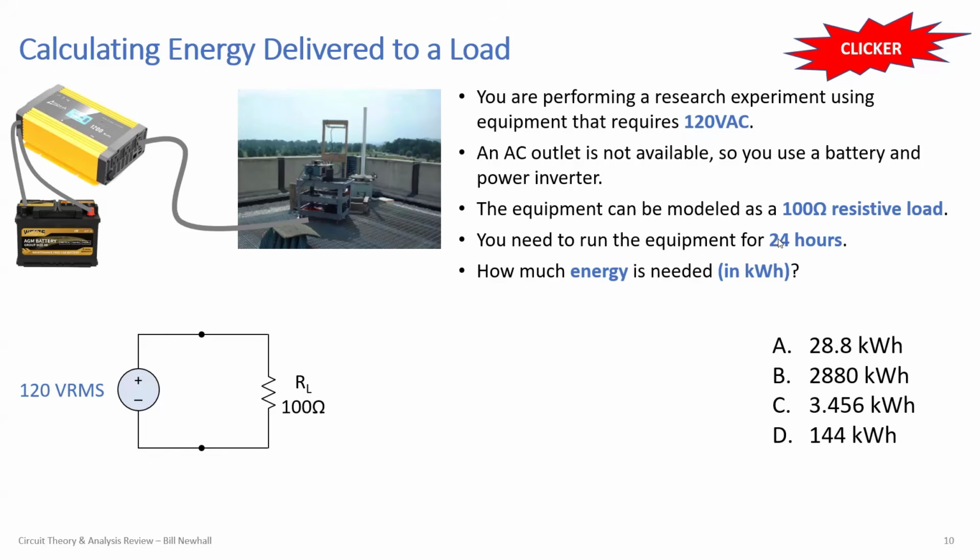All right, take another minute. And so a lot of these calculations can be dissected by the units. We can figure out power from the voltage and the resistance, convert that to kilowatts, multiply that by hours, which is how your house power is measured.